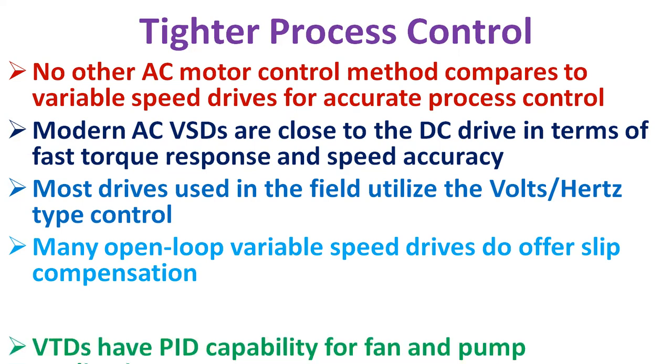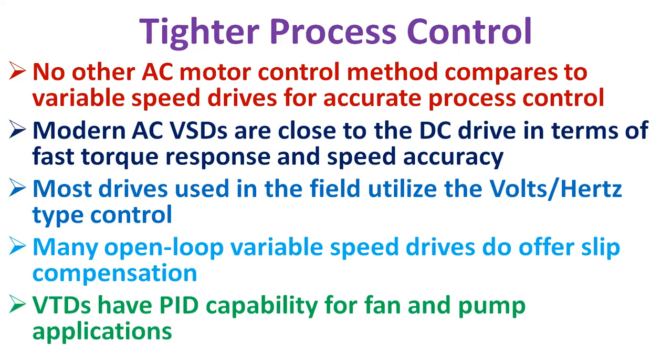Most drives used in the field utilize the volts per hertz type control, which means they provide open loop operation. These drives are unable to retrieve feedback from the process, but are sufficient for the majority of the variable speed drive applications.